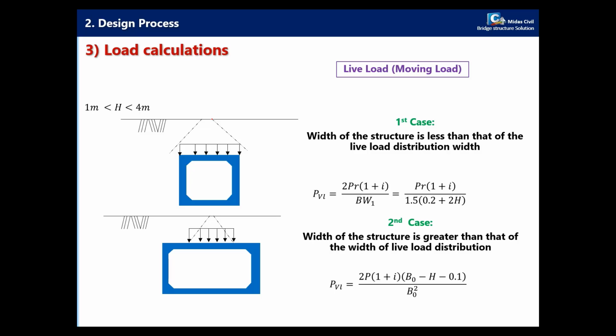Based on H, the height of the ground, if H is greater than 3, the influence of the truck will be neglected. But for values in this interval, you need to consider the influence of the live load on your structure.